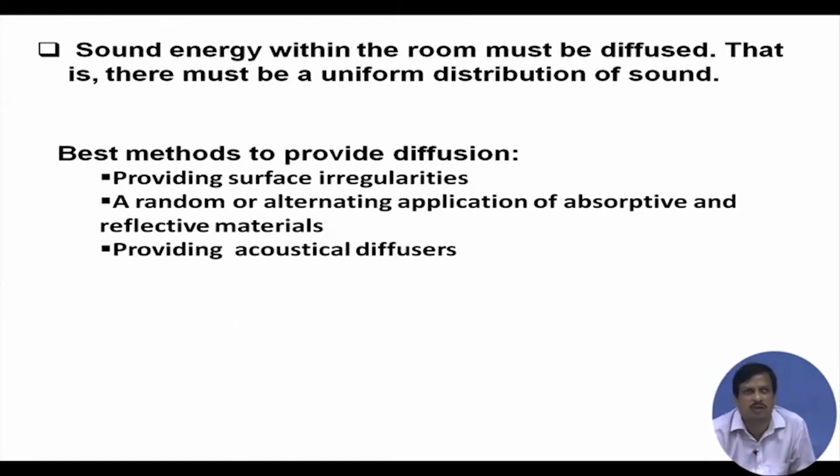So, the front part of the stage is reflective. I can do some mural or wooden work in the front part of the stage. If you visit our Kalidas auditorium here, you see the front part is made with a painted wooden design. So, it is an irregular diffuse design, but its reflection coefficient is much higher, so that it reflects the maximum energy.